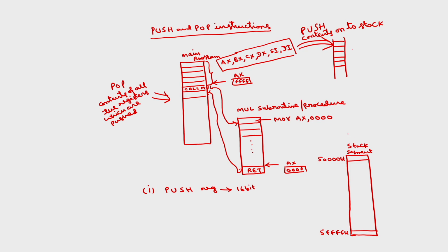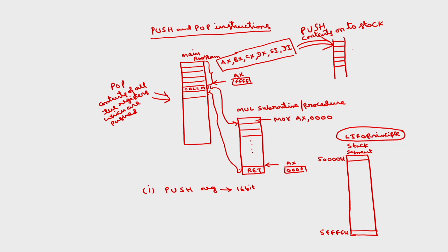This stack operates on the last in first out principle. Whatever data we are going to push will enter here like this. While taking back, the data which was inputted last will be outputted first. This is something like arranging plates in a rack. In a rack I first insert one plate, above that another plate, above that another plate. While taking back, first I take the plate which I inserted last. So, in a similar way, this is the last in first out concept.